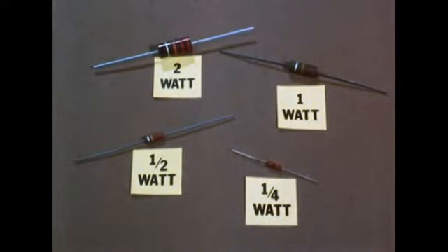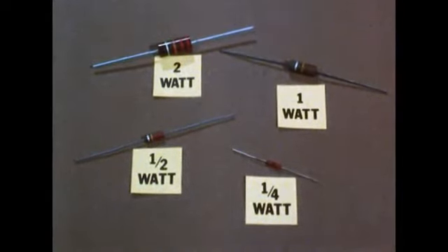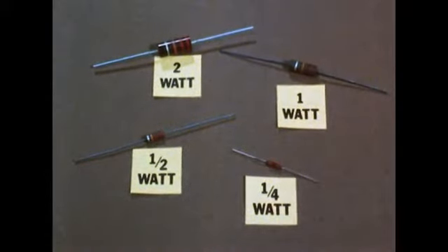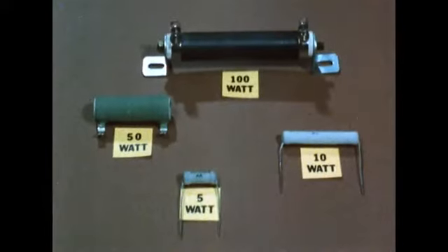Resistors also absorb power, and so they too have a power rating in watts. These carbon resistors all have the same resistance, but the rate at which they use up electrical energy differs. So their power ratings also differ. The bigger the resistor, the higher the wattage they absorb. When resistors of higher wattage are needed, wire resistors are used. They usually range from 2 watts up to 100 watts, and special ones of even higher ratings are available for power ratings in excess of 100 watts.